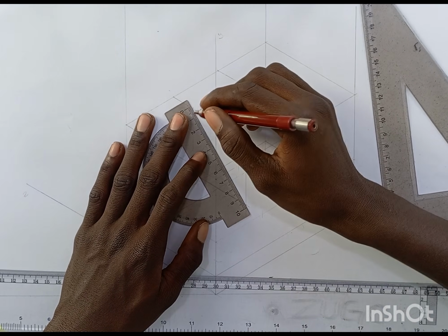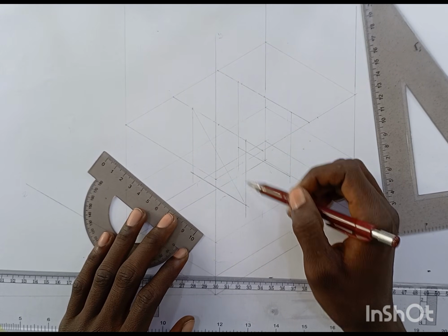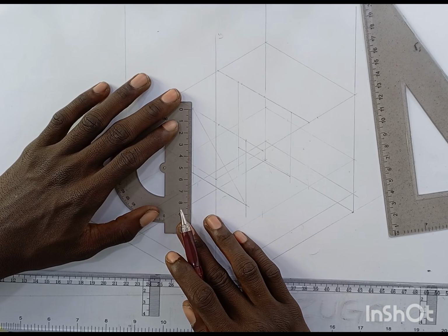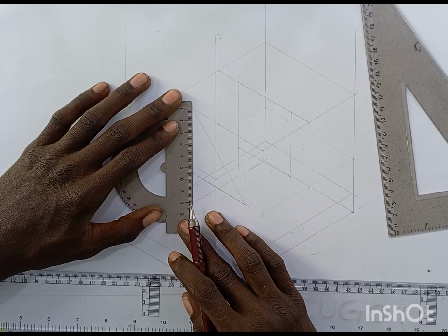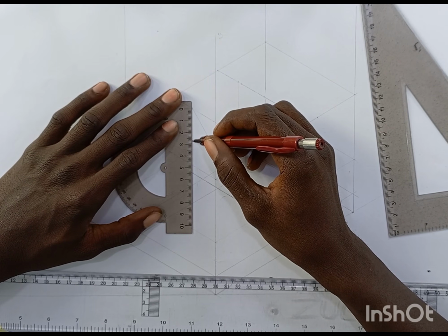Now, the next thing here, to draw my ellipse across this side, I will divide this across the diagonal like this. Okay. Then here we have these two angles. I will divide this line into 2 and divide this line into 2. Same with this. Since our diameter is 55, I'm going to measure 27.5 from one side, which is going to give me half. Here is my 25, 26, 27. 27.5 is at the middle.